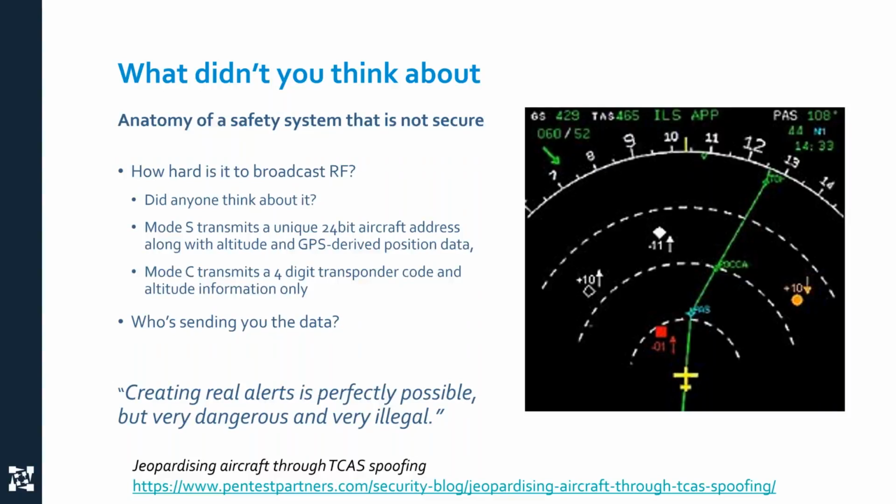So instead of just showing me this graph like I see on the right and showing me, are these planes above me or below me, what direction are they at, what vectors do we have, what's the distance, what's the speed, how soon will I encounter them, it actually has a really simplistic system. And I encourage you to go watch a video. But basically, if something's within a reasonable zone and potentially an issue for you, it says "traffic," which is pretty simple. And now you can pull your eyes back into the instrument panel, take a look.